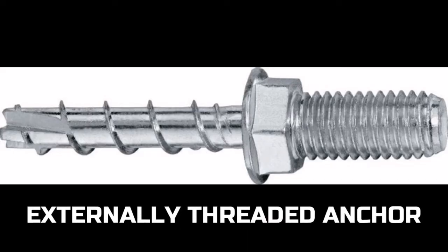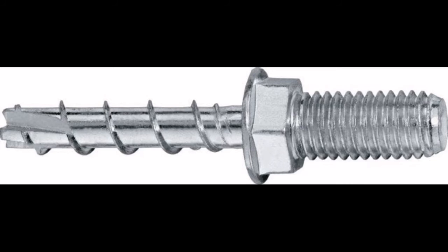Externally threaded anchors. Externally threaded anchors made for concrete anchoring have an exposed threaded stud. A nut and a washer may be included and a setting tool is not needed. They are not designed to be removed or reused.